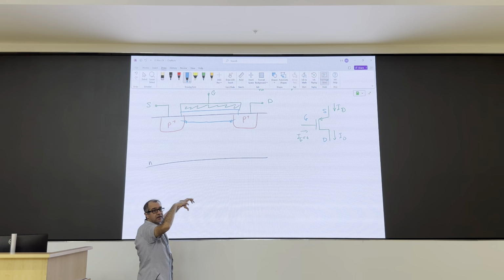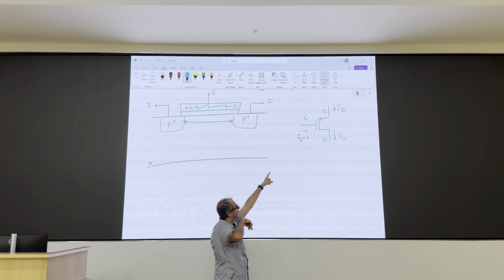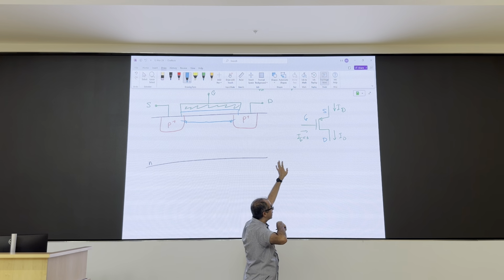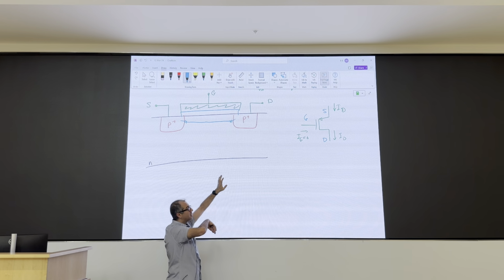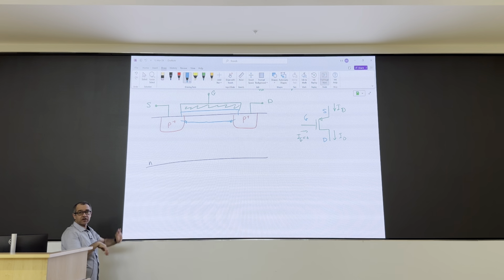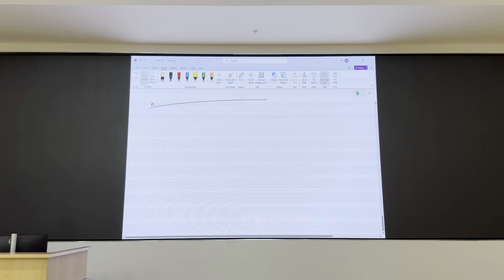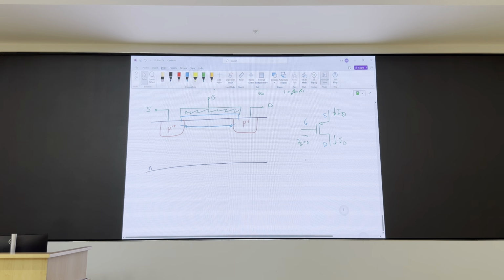Like before, a lot of discrete devices have the body and source terminals connected internally, because usually the source terminal is at a higher voltage than drain. If they do that, it becomes asymmetric. But for integrated devices, we have the choice. You make sure that the body is connected to the most positive voltage in your circuit. Now, the main difference here is that the threshold is negative.